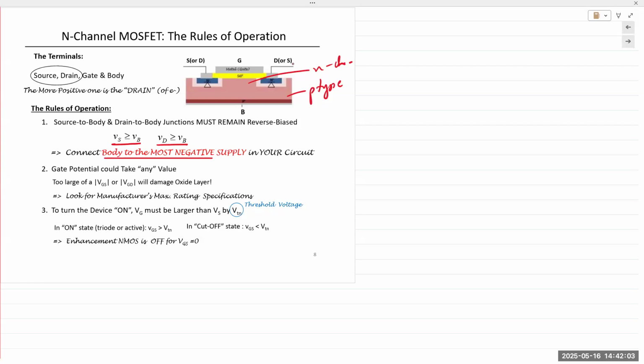The question being asked is if we reverse bias, would it damage the device? No, we are not applying anything in excess of, like, 5 volts, let's say. Modern devices run at even lower voltages, digital logic voltage, 3.3 volts. So very, very small. As long as it's off, that is sufficient. If you're working with power MOSFETs, higher voltages, higher currents, then you might be able to apply larger reverse biases, but it's not going to damage it.